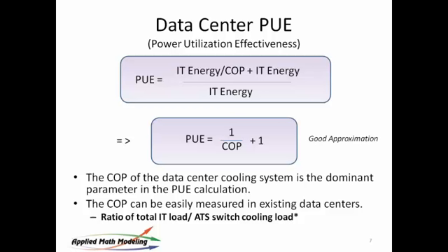So let's say, and this feels right, Liz, if you know what I mean, for example, if we assume our COP is 4, which is a pretty good one, then our PUE is going to be 1.25, right? Yep. In fact, if our COP is 5, which is a very good number compared to the charts I was showing you earlier, remember the range was 3 to 5, then my PUE is going to be 1.2, which I defined earlier as being excellent.